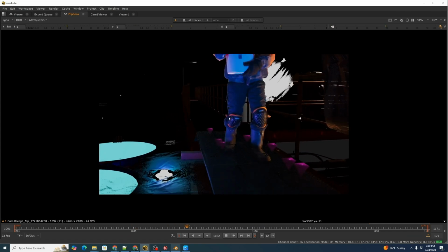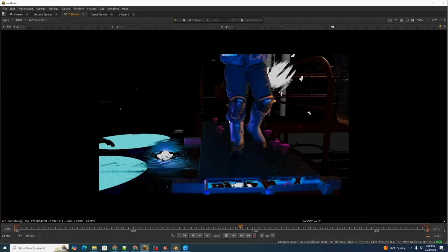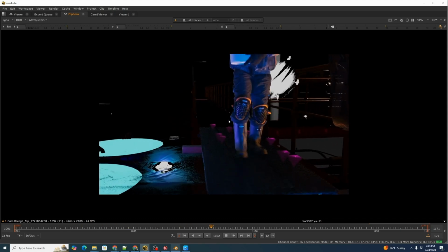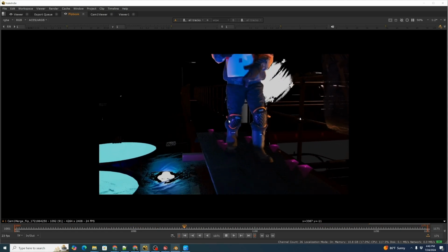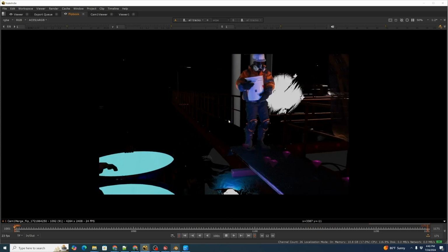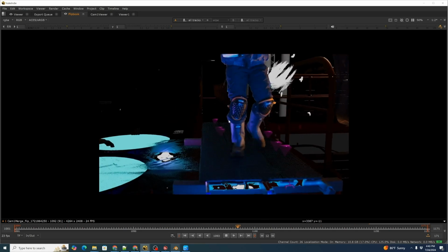So it's important to understand what we're doing here. We started with our JetSet onset data. We created our initial Blender render file. We then exported a script into Syntheyes with our onset information on it, including our scan and our track data. We generated a new solve and pinned it to the original onset tracking data information and scan information so that when we solved it, we maintained our coordinate system and maintained our scale and our frame so that it drops back into the 3D frame.